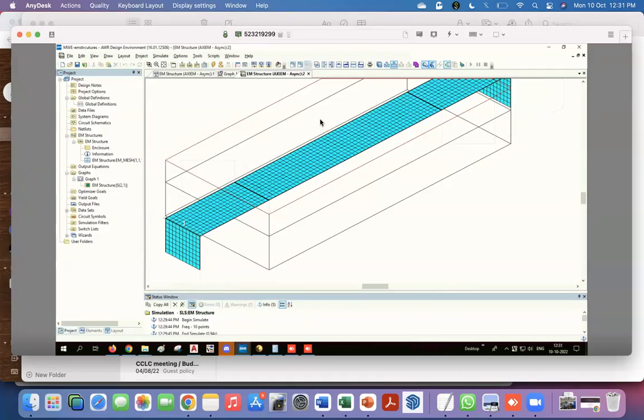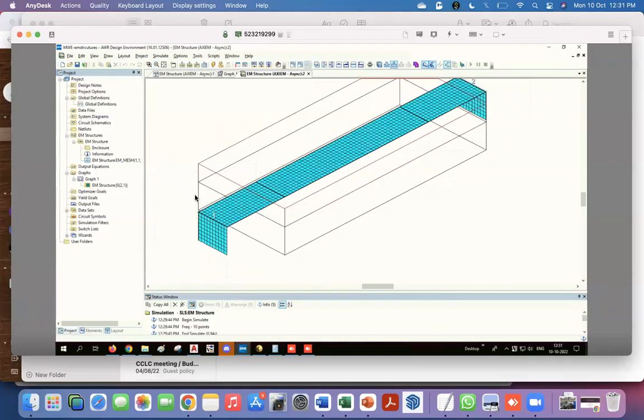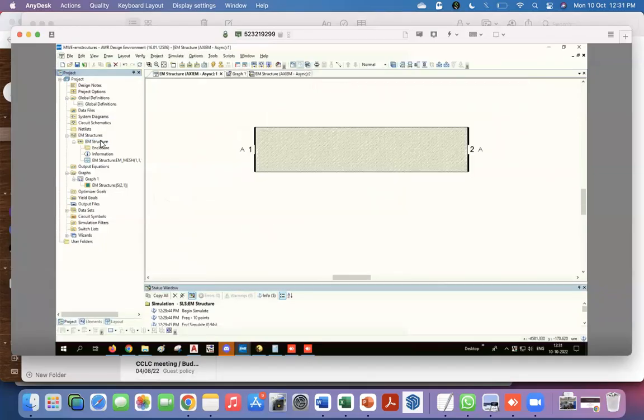It's not really related to the understanding of the microwave structures, but more about how we use these kinds of softwares so that you don't get wrong results. Just a warning, especially with EM structure simulations: what you get could be completely misleading if the simulator is misbehaving or you have set it up in such a way that the simulator doesn't do things right. So this is the mesh part. So let's go back to the